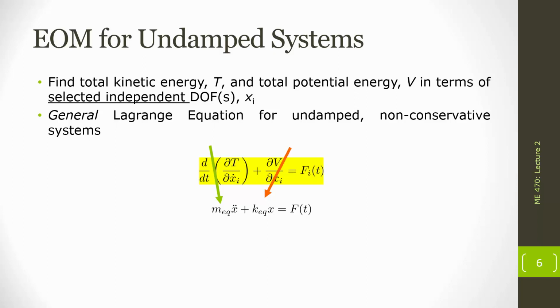For the most part, after the point at which we are doing this differentiation using our Lagrange equation to get our ordinary differential equation, the bottom term here, I'm typically not going to write the EQ after the M, the K, or the C. So in general, if it's just a little m, that is referring to the equivalent mass in our system. A little k is referring to the equivalent spring constant of our system.